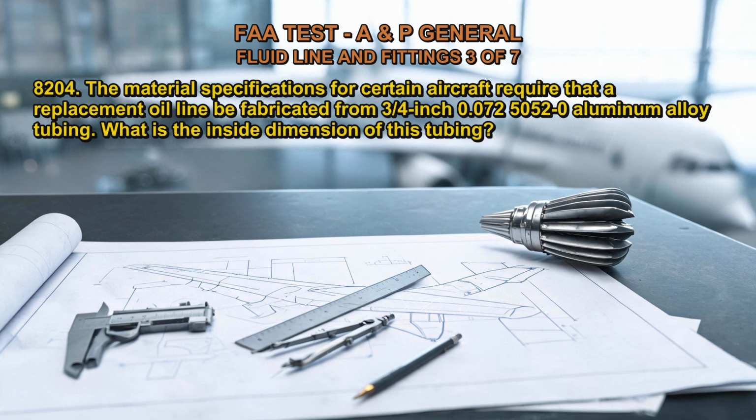8204. The material specifications for certain aircraft require that a replacement oil line be fabricated from 3/4 inch 0.072 5052-O aluminum alloy tubing. What is the inside dimension of this tubing? A. 0.606 inch. B. 0.688 inch. C. 0.750 inch.